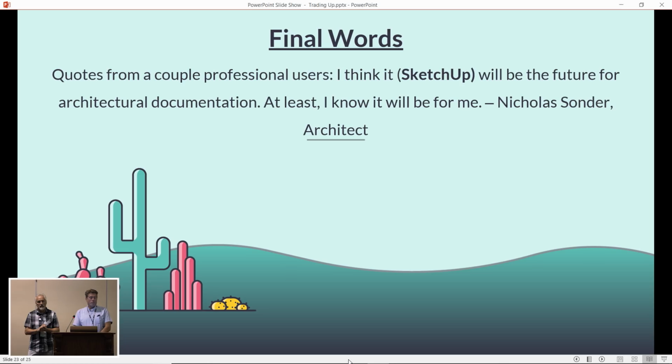So the way I deal with how to make the drawing pretty is I layer up viewports. I do a combination so that in Layout you're producing a drawing that consists of a raster viewport, which captures all of the textures and shade and shadow and fog effects that you can do in SketchUp that make the model look really amazing and dynamic. And then I'll overlay on top of that